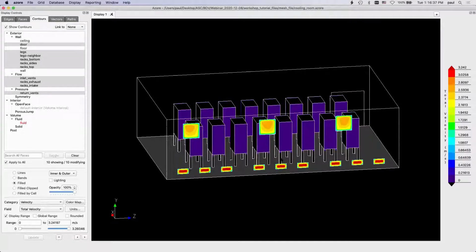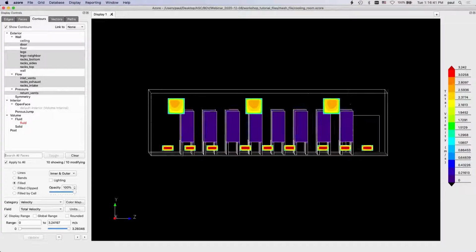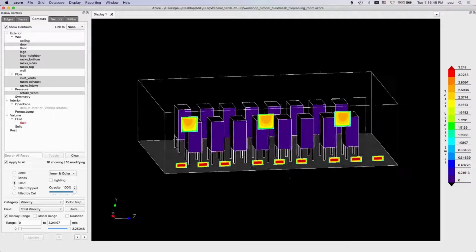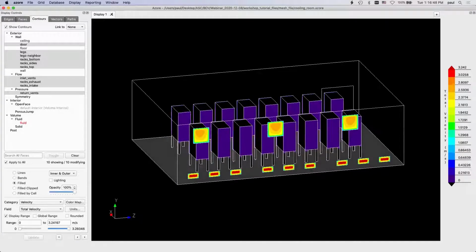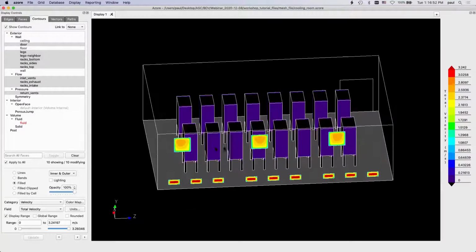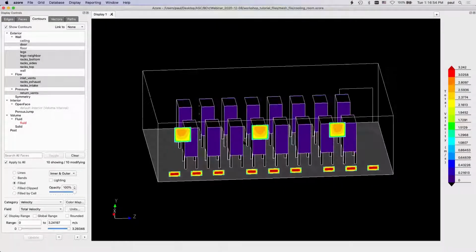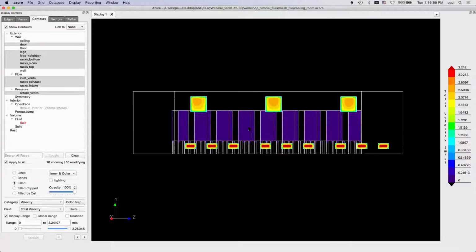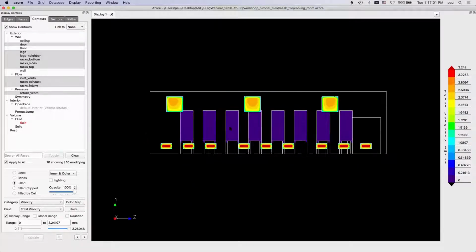I'd like to cut straight through in a plane normal direction. It's kind of hard to line this up right on a direction, but another quick step is to rotate it. We're using our left mouse button and dragging. While you're doing that, if you hold down the shift key and then drag, it's going to snap. So that makes it very easy to get a view exactly end on where I can make my cutting plane. So now I'm going to try that cutting plane again.